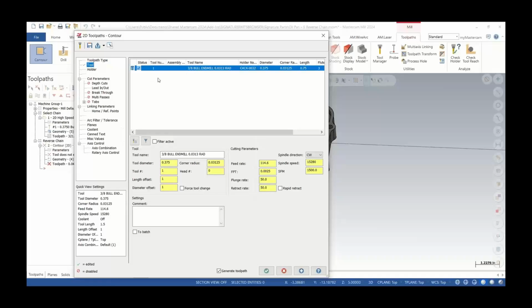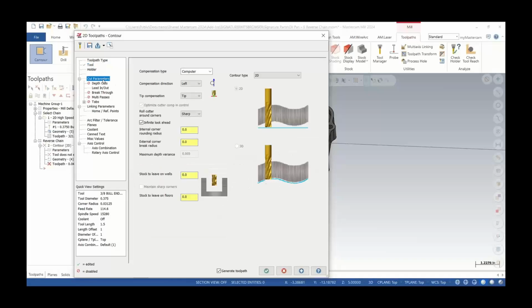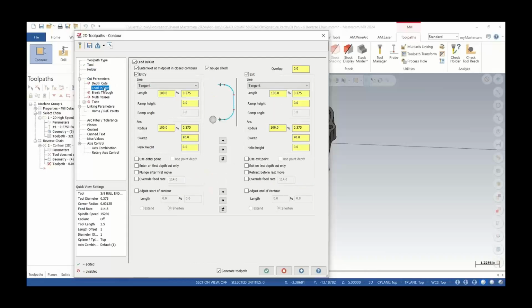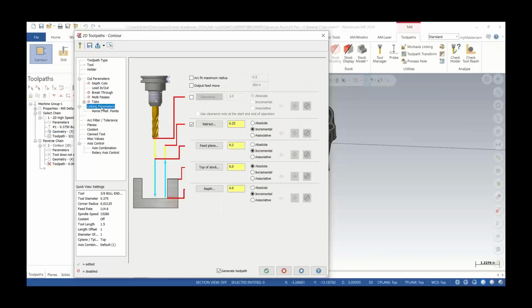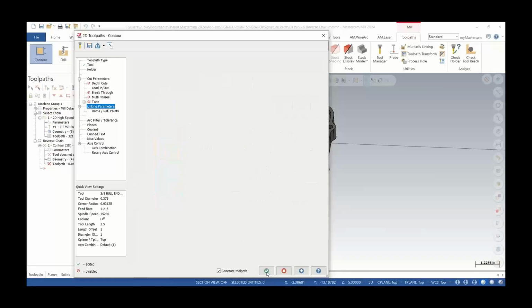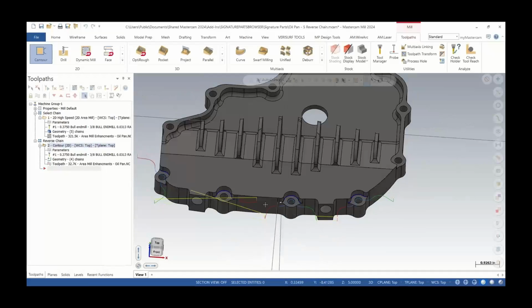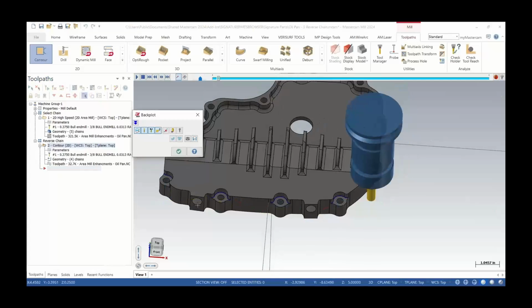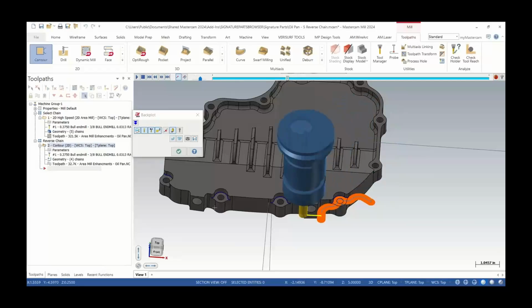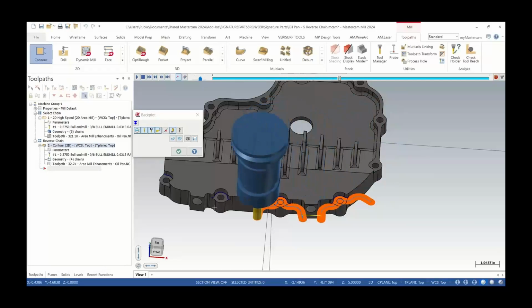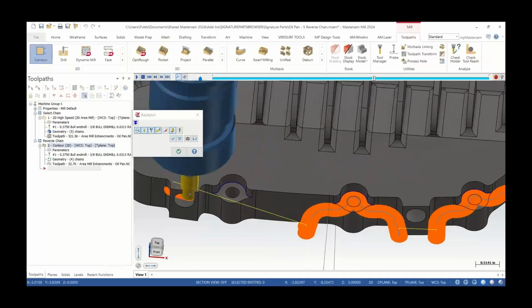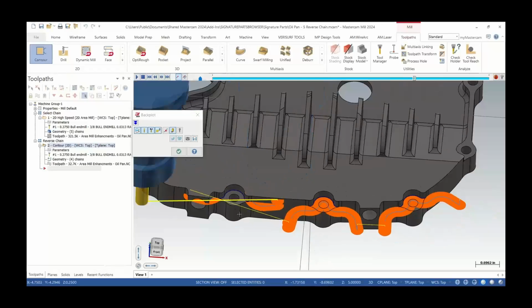I'll just use this full end mill. I'm going to leave the leads and basically everything alone, just standard as is, and I'm going to hit the green check mark. So as you can see, 3 out of those 4 are correct. If I turn on my simple verify here, I can see going through that location, and then we're crashing on that other chain.